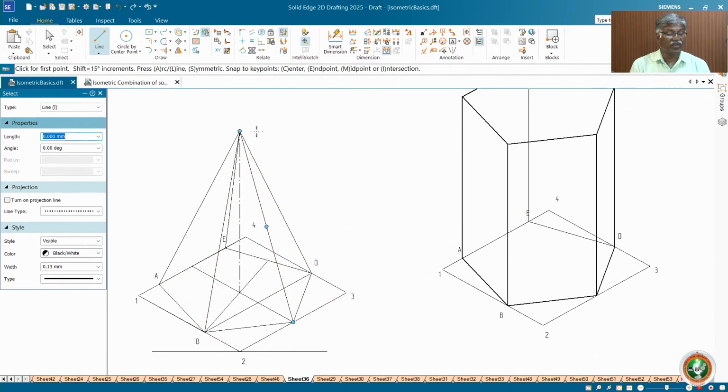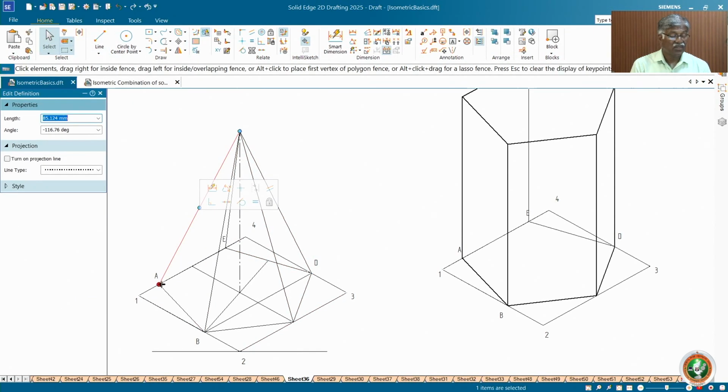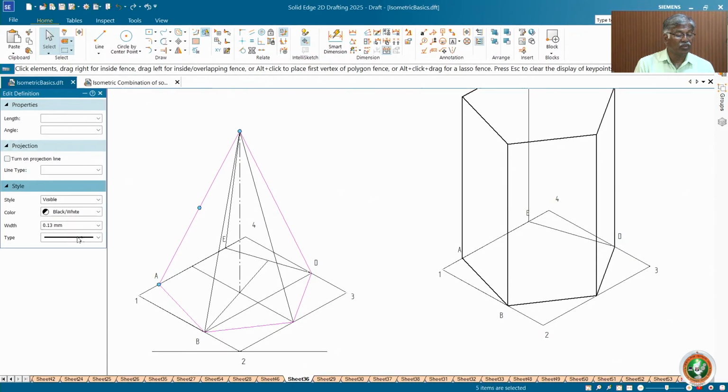Now no top face, only apex. So the base is not visible. So boundary lines completely dark. Dark all boundary lines first. This is as good as completing the solids projection. Okay, projection of solids visibility, same type. I chose all the boundary edges and made them dark, 0.5.